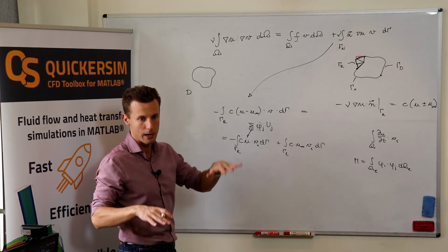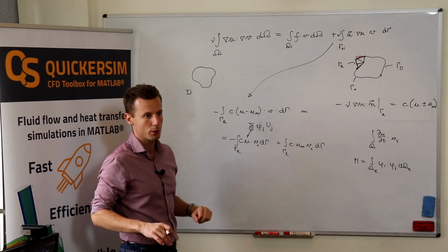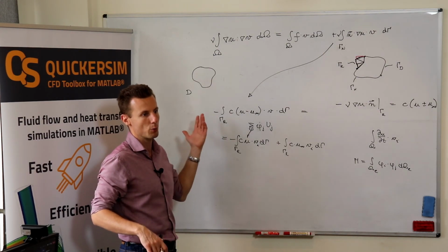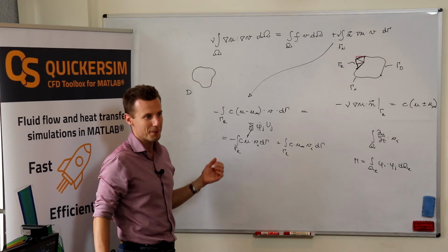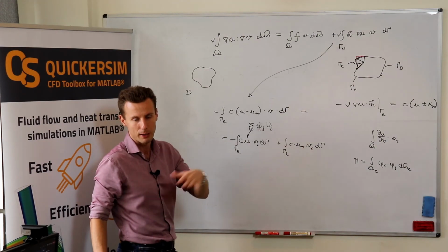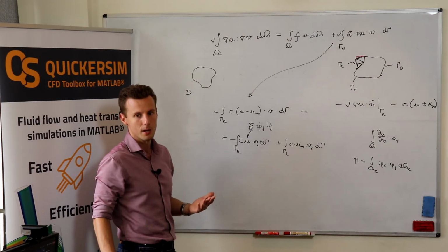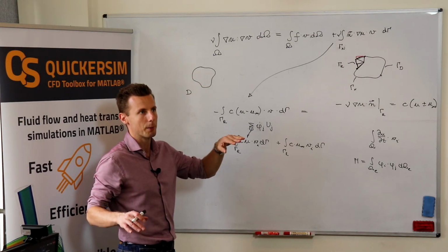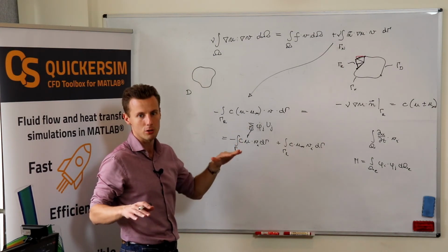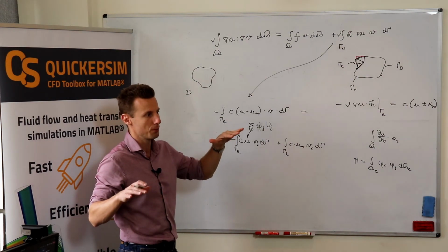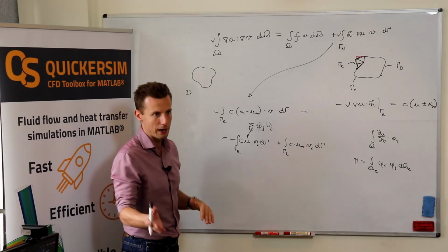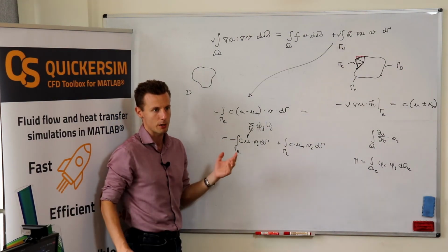You can choose any temperature level where the solution will be okay, right? Because for the heat transfer only the gradients matter and nothing else. If you've got Neumann boundaries, you haven't got a prescribed temperature level at which the temperature solution should be located. You only have this if you define the Dirichlet boundary condition.